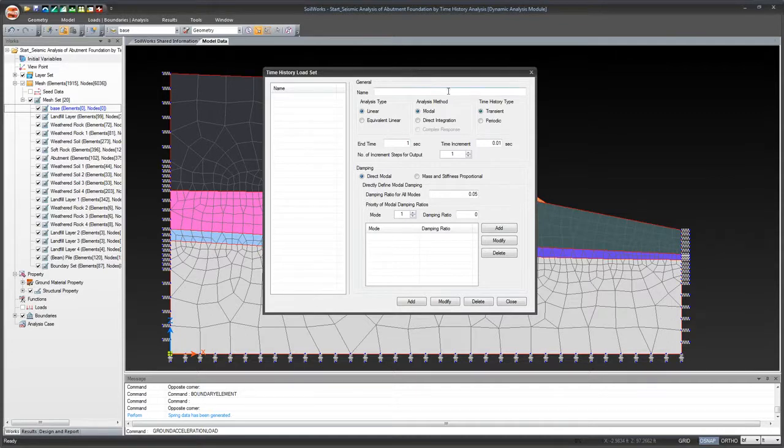First, let's create a long period wave. We'll have a long period and a short period wave, because we want to run the analysis for two types of earthquakes. One's a long period, one's a short period, and we'll get them from the database, which I'll show you in a minute. But first, let's define this one. We're just defining a load set. The properties haven't been defined yet; we're just naming this blank set, and later we'll assign the properties to it.